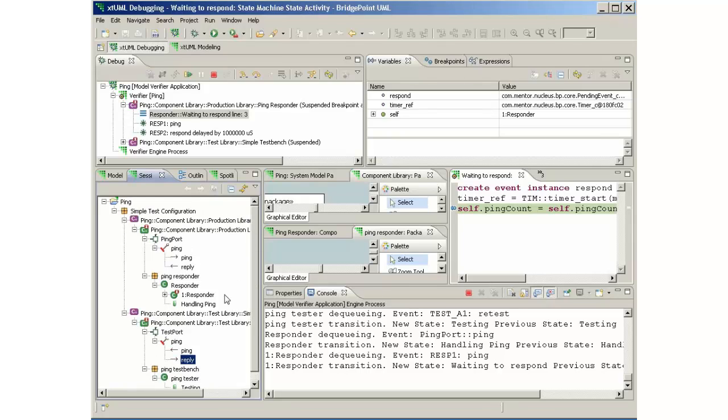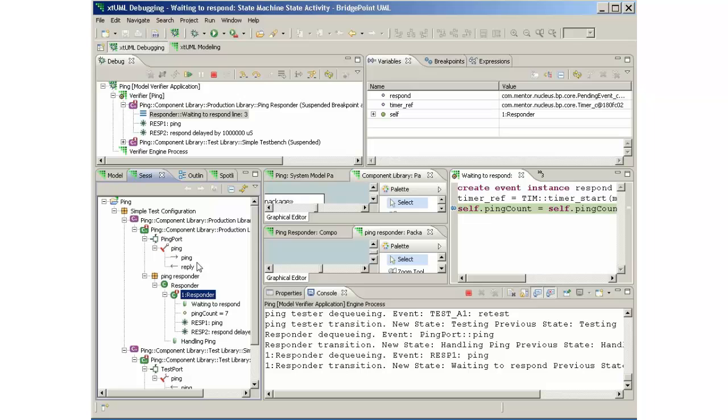If the variables view shows a set of values filtered according to visibility in a given context, the Session Explorer shows the big picture. It doesn't filter values, but instead organizes them into a tree that you can explore as required. The tree is organized by, from top to bottom, component, class, instance population, attribute and association value, and finally current state and pending events.